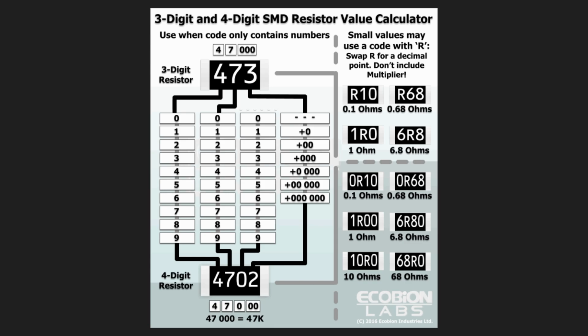Okay, if they give you 400 zeros, it's just the same. Why they make this so hard to read is because it is easier to print on the PCB, to save space. Yeah, this is the only reason why they do that.